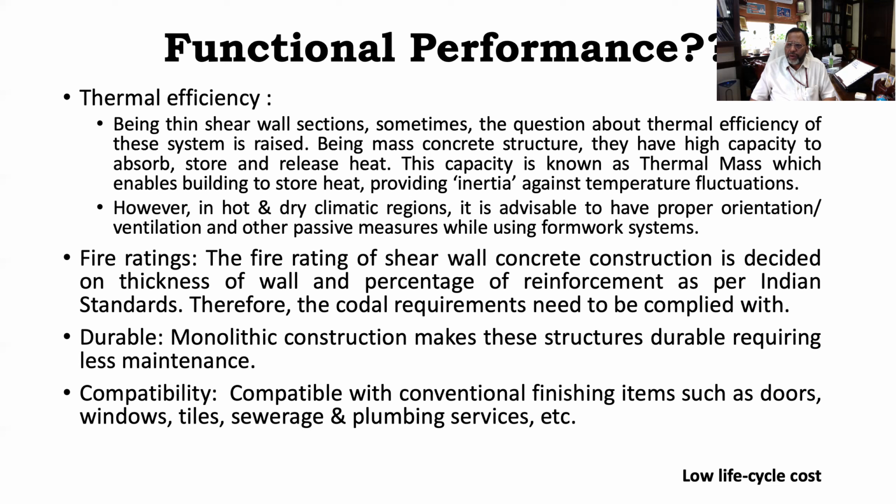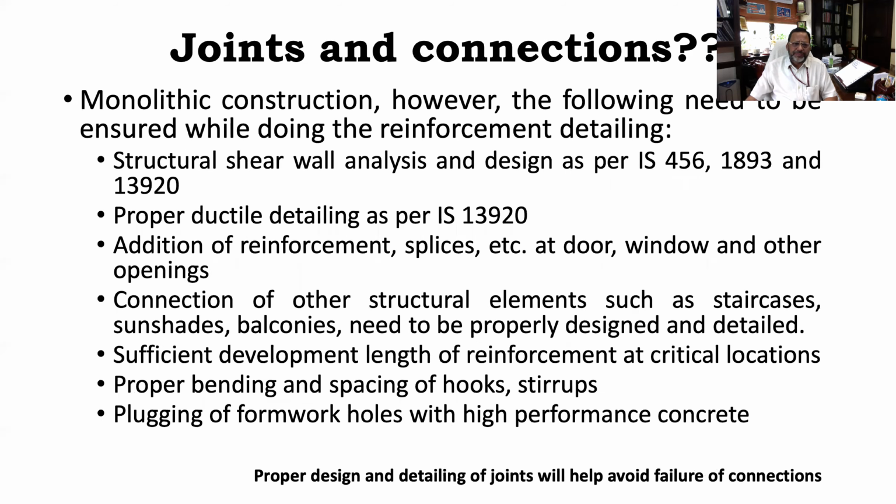The structure is durable, better structurally, monolithic, and has no leakages. So the durability is enhanced. And it's like any conventional construction. When you do it with RCC conventional construction, it is similar to that. Compatibility with the conventional finishing items such as doors, windows, tiles, and plumbing services does exist here as well. Joint pin connections are absolutely no problem because it's monolithic concrete construction.